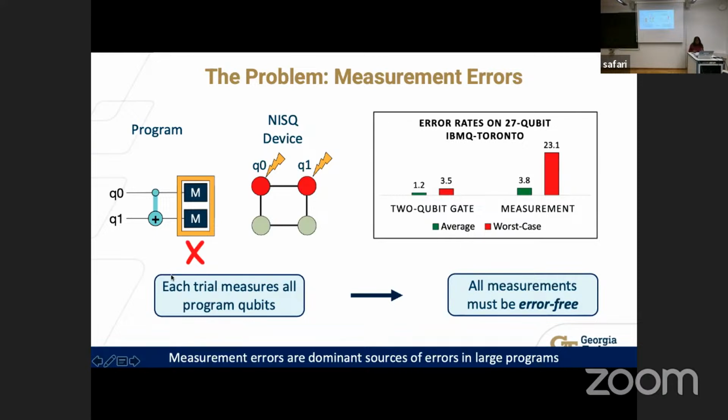And this has to do with the fact that in most cases, you are actually sharing some of the resonators that leads to crosstalk, or you are actually dealing with a lot of components, analog and digital devices, amplifiers, that are spread out across different thermal domains. So there's an element of thermal noise. And that's what introduces errors in this whole process.